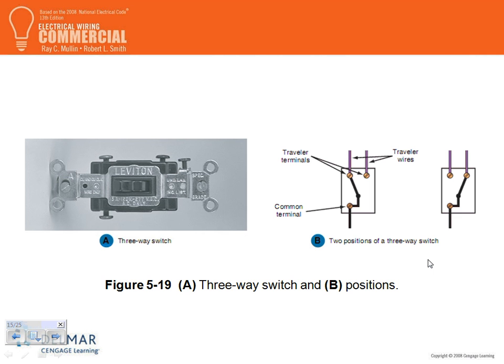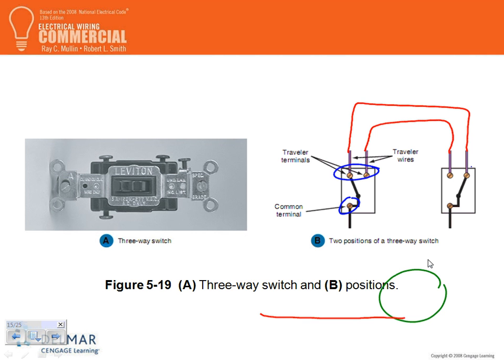Okay, 3-way switches. Just a quick review, guys, for the 3-way switches. Mr. Urbab, 3-way switches always have 3 conductors. You have your travelers on one side, you have the common on the other side, and when you wire, I hope for Pete Ricard's sake, that you guys can come over here and grab these two together, right, when we wire them. And if I have my fixture sitting right in here, the first thing you're going to do is tie the two together. The third one, now which switch, and here's my neutral coming to my fixture.